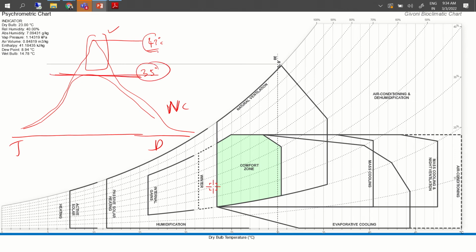This is where we make a lot of errors, especially when we do building energy designs. We don't design for 43 degree extreme 1 hour conditions in the weather file. We can't design a system that can tackle 43 degrees Celsius. We are actually looking for the average higher temperatures, which is 35 degrees Celsius. So we design buildings for this. We don't design buildings for 43 degrees Celsius.